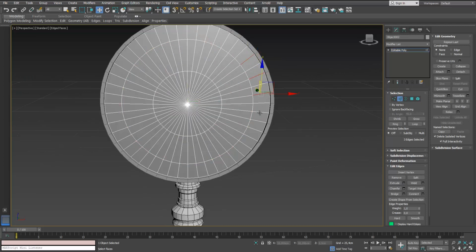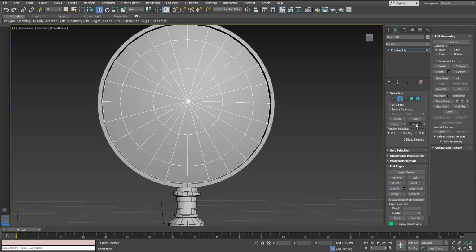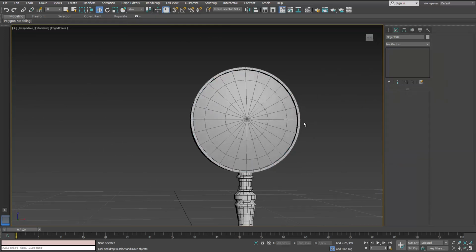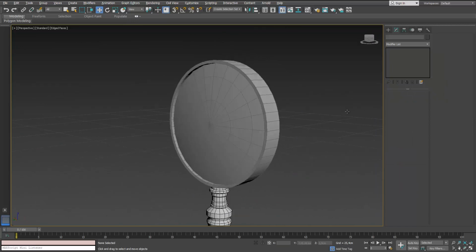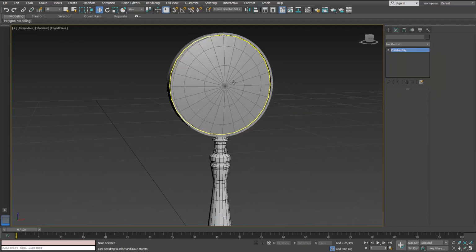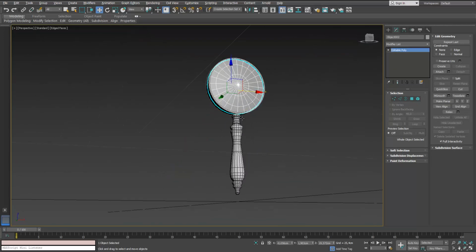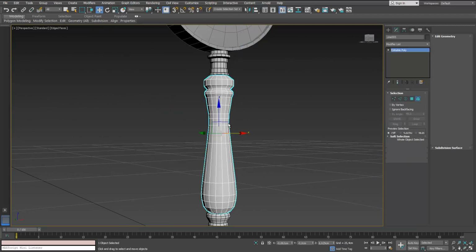Even though here it does have a lot more than necessary, so in order to remove these edges, you're gonna keep holding Control and then backspace. So for example, that glass, that many polygons in it probably is not necessary, because the frame is covering the imperfections of it when we reduce the poly count. So probably that area was fine.